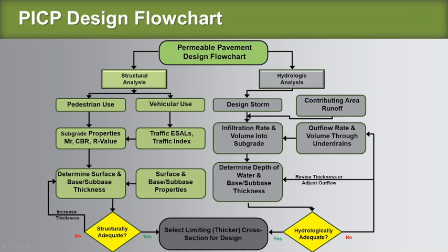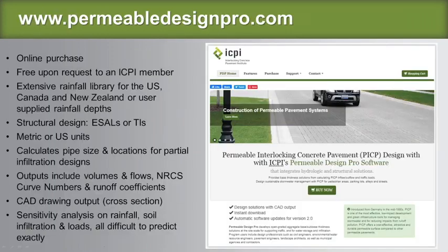If a pavement is just thick enough to handle the traffic and just thick enough to handle the design storm that you want to do, then you've got a balanced design. And so ultimately, if you don't, you may have to have a thicker pavement because maybe I'm building a parking lot to handle only cars in Houston, where a 100-year storm is going to be 15 or 16 inches of rain. And so it's going to have to be probably thicker to accommodate the hydrology, the water, than it is to be handling the cars that are there.